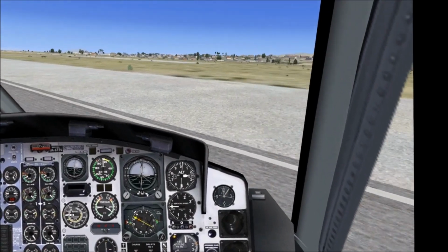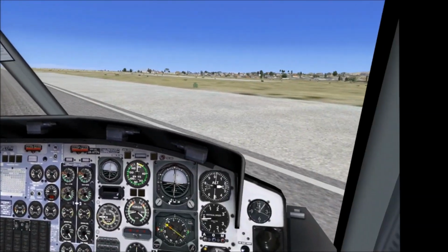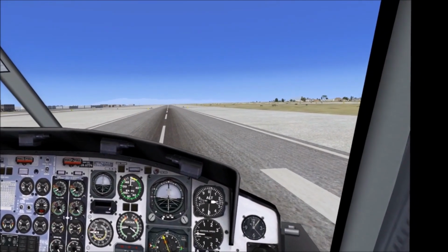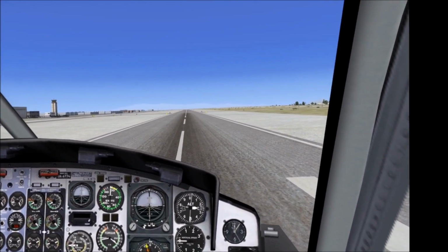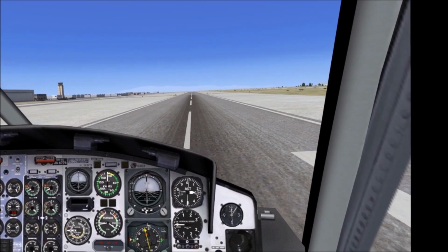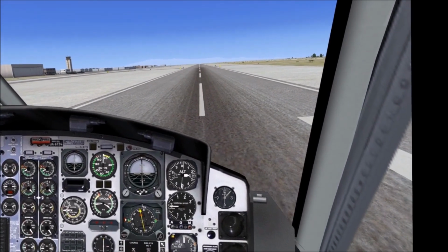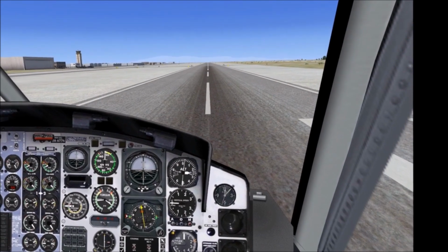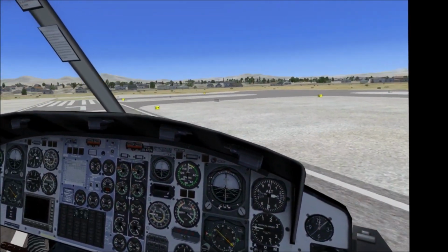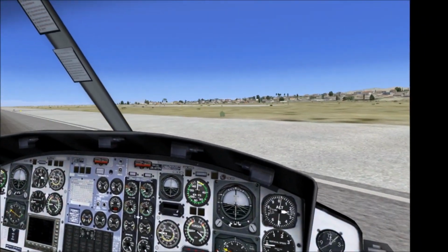It also takes a lot longer to stop a right-hand turn than it does a left-hand turn. So it's not unrealistic for it to be a slower build-up with the right-hand turn, but with the left-hand there's this hesitation, like the aircraft is unsure of what you just did.